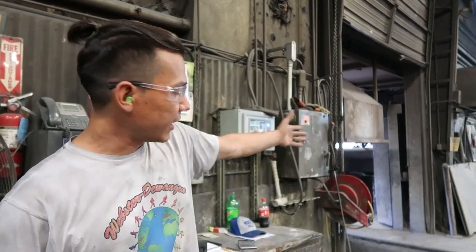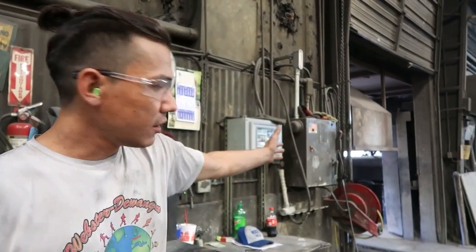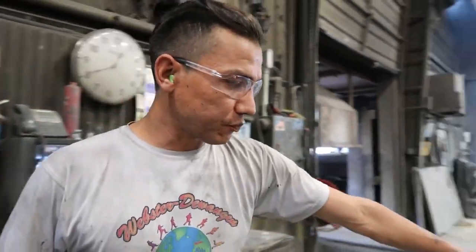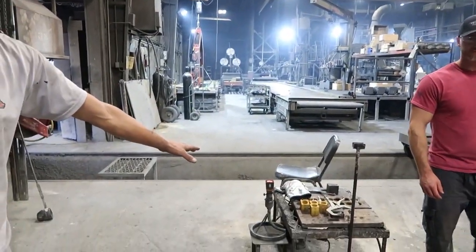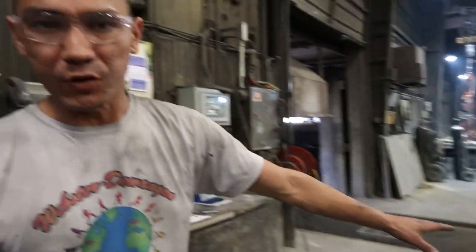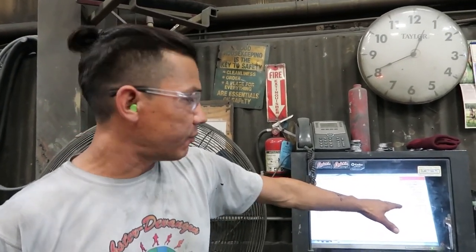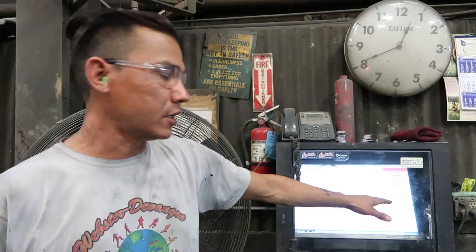And then that gets put into our holding ladle. It goes out there, and I take a test. I chip the test off of every single ladle before and after, so we can check out the chemistry changes and the quality of the iron. And this is where I get my result. The reading I have right now, that's the perfect iron. That's right where we want to be, 350, 220.